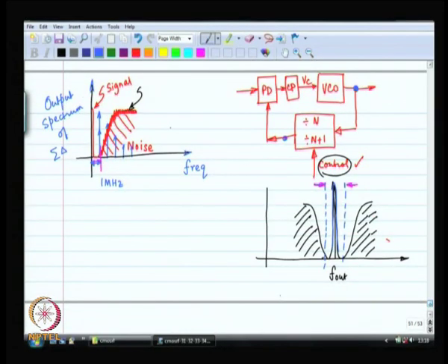modulators. Then we saw that suppose I make a higher order modulator without paying too much attention, then I am going to have phase noise problems anyway. Okay. So, you have to design the sigma delta modulator carefully enough, so that you do not pollute your voltage controlled oscillator output.